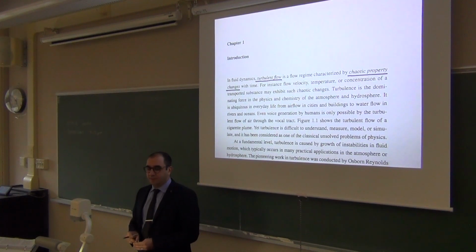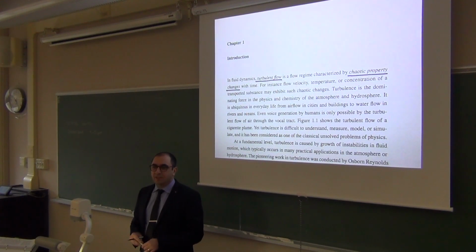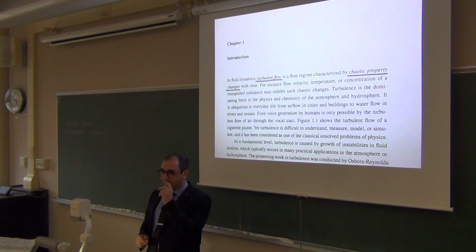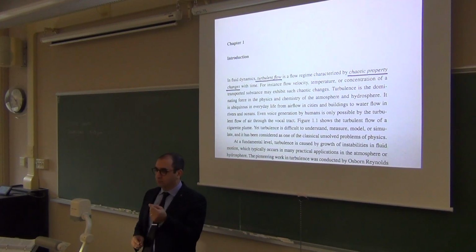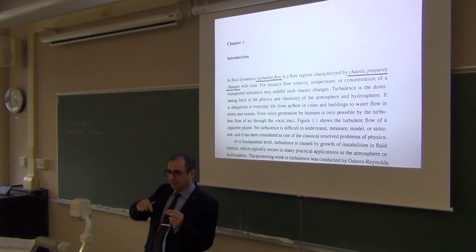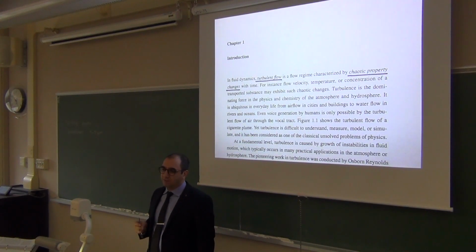So if this flow or airflow in this room is in a way that these properties change chaotically and I can't really well predict, then the flow is turbulent. And I can assure you, if you bring a very sensitive anemometer, the device that measures airspeed or temperature or humidity, pressure, if you put this very sensitive sensor here and you record its measurement, it's going to be noisy. If you look at the measurement, it's going to be lots of fluctuations. And that's the nature of turbulent flows.